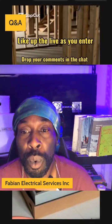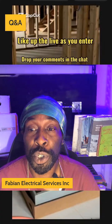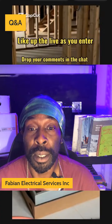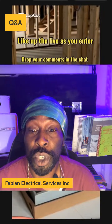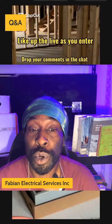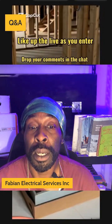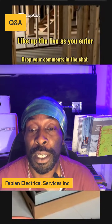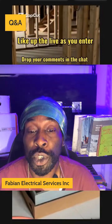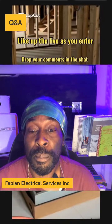We are live. Welcome in, brothers. Tonight, we are stopping into the workshop lab to tackle a commercial code calculation mistake that breaks a massive percentage of green helpers and residential installers the second they switch over to commercial job sites. Sizing your multi-gang box fills: a lot of helpers think you can just keep cramming conductors, wire connectors, and heavy device bodies into a standard metal 4 square container as long as the cover plate screws down.